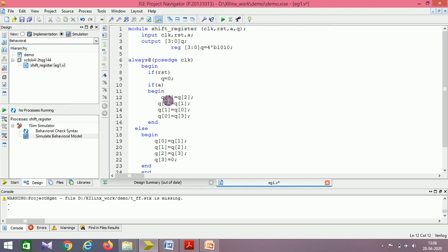So that's why, before this Q3 bit gets vanished, make sure that you define one temporary register and assign your Q3 value to it, so that its value is retained, and in the temporary variable your Q3 value will be there. So that value I'll fill it here. This makes the rotation operation successful. Try to check it, try to implement it, take it as an assignment for you.